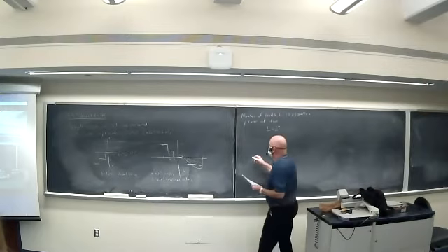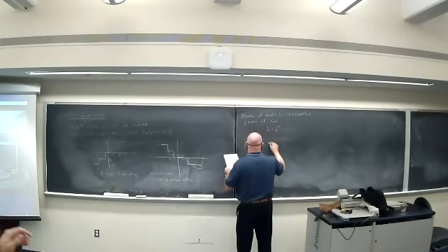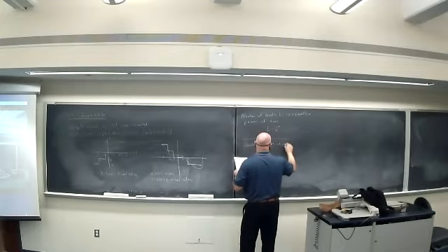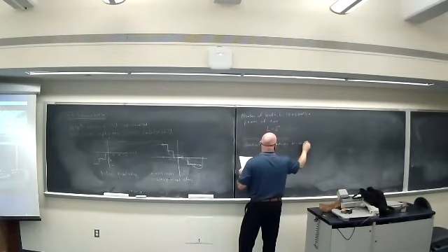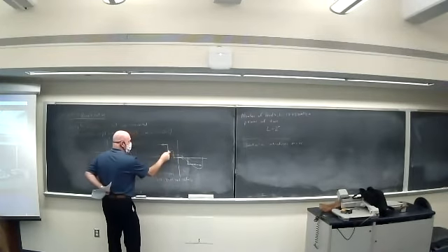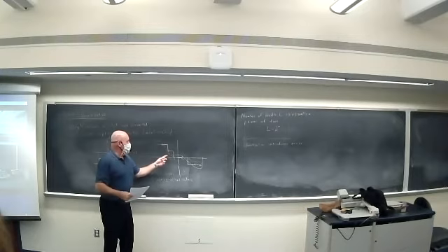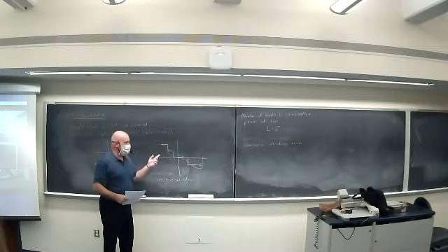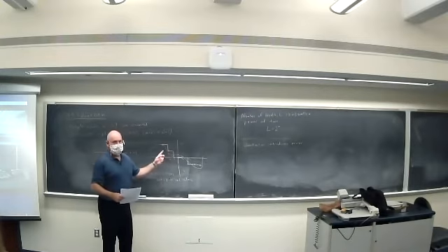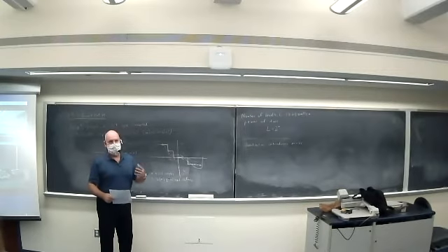But you can see that quantization introduces error. Once I've done this rounding, I don't know whether the original sample value, once I've rounded to 1, could be anything between 0.5 and 1.5, right? In this particular case, the original value is 0.5, but once I've done that rounding, there's no way for me to recover the original sample value.